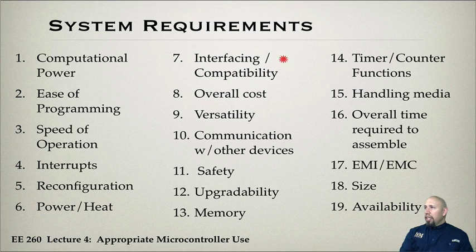What about the ability to interface or the compatibility? In other words, how easy is it to connect up analog signals? How easy is it to connect up digital signals? How easy is it to, for example, can it handle TTL and CMOS, or do you have to do some kind of circuitry to convert from one to the other in order to use it? So that's the issue of compatibility. Is it CMOS compatible? Is it TTL compatible? Okay, so those compatibility issues are important. Maybe there are certain devices that have a specific plug, and you can plug it right in, or do you have to come up with your own plug to plug it in?